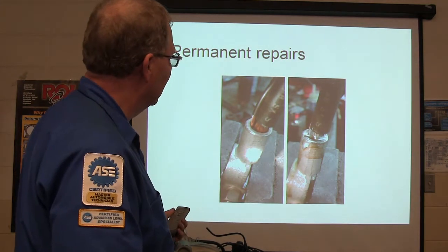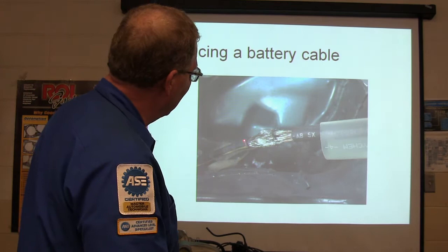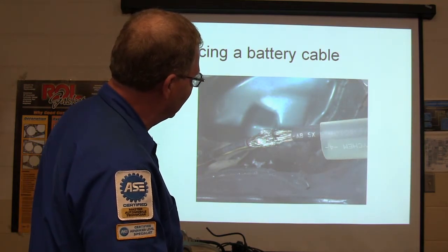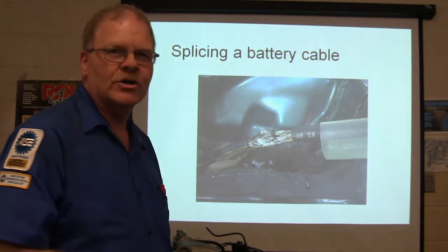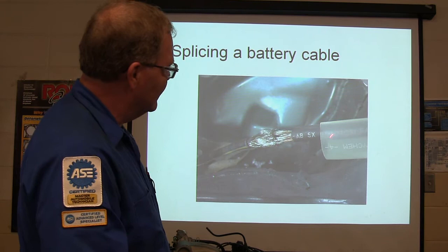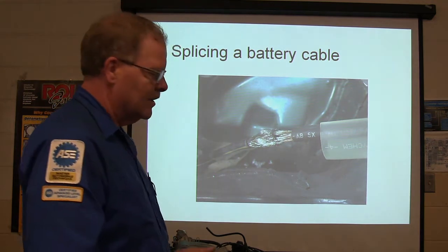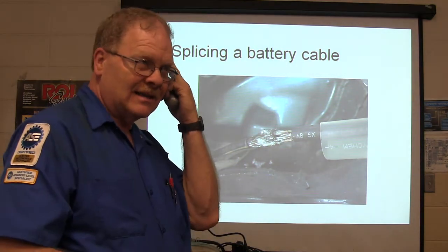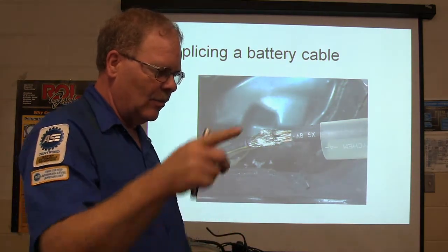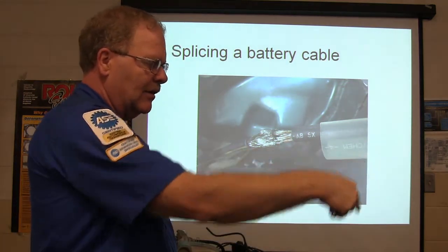So that's not complicated. Back here, when I got back to the place where I finally had some good wire, I got a new piece of wire and meshed it together with that one, and then I used a torch to solder that together really good. Then I put a good piece of heat shrink on it, so I didn't have to replace the whole cable. Now, replacing the whole cable wouldn't be such a bad thing, but a lot of times on these, the cable will go and ground here, and then it goes over and grounds somewhere else.